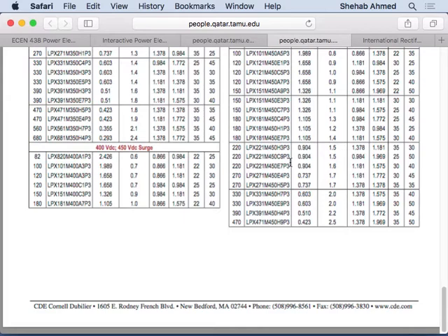Again, as an example, I said that these rectifiers may be something where you can tolerate it. A lot of these front-end rectifiers convert everything to DC, and then you do what we have in the project. You take that rectified waveform and use a linear regulator, or take that rectified waveform with ripple and convert it to a different DC voltage. So take that 18 volt with ripple and convert it to 5 volts with less ripple using a switching power supply after that. That's typically where you would use something like that.